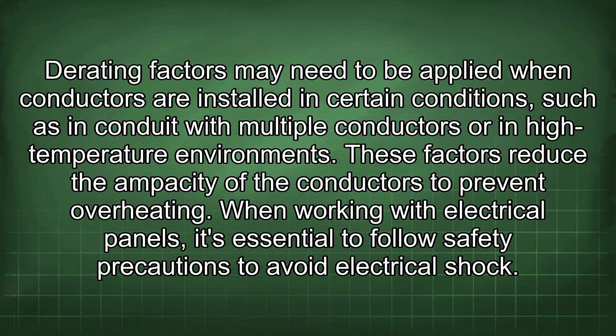Derating factors may need to be applied when conductors are installed in certain conditions, such as in conduit with multiple conductors or in high-temperature environments. These factors reduce the ampacity of the conductors to prevent overheating.